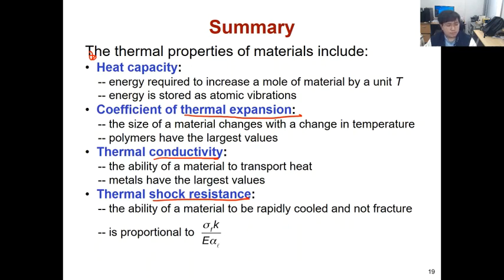And after covering these two topics, we learned about thermal shock. Thermal shock can arise from extremely large temperature changes, for example, in space shuttle or missile systems. At that time the surface part will experience a large shrinkage or expansion relative to the core part of the substrate, so the surface part will experience some fracture. To overcome this, we should design the solid material properly.